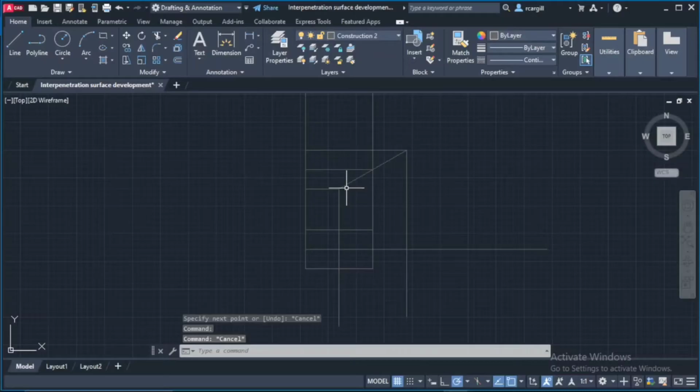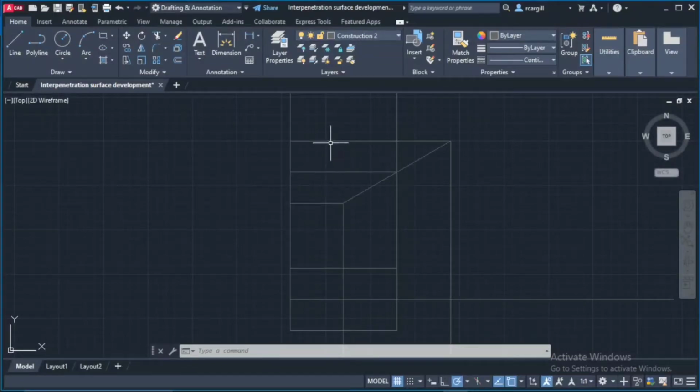All right, now from here, what we want to do is this. We can now draw the ellipses. However, remember that there's a hole of 50 millimeters that is running through this tube. So we also need to draw that hole. So from this center line, I'm going to offset this center line by 25 millimeters up and down. And I'm going to do the same thing right here. Now, the reason I'm going to offset by 25 millimeters is because the hole diameter would be 50. So 25 would be half of 50.